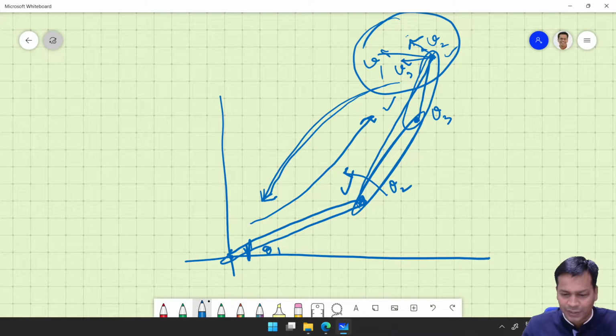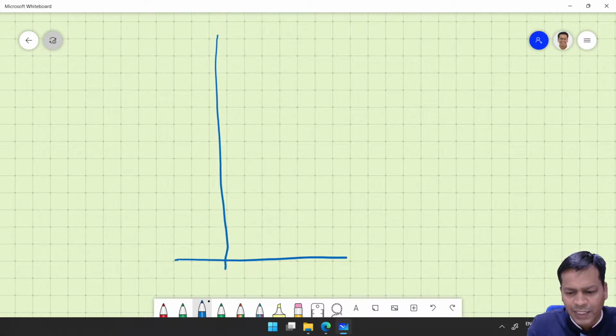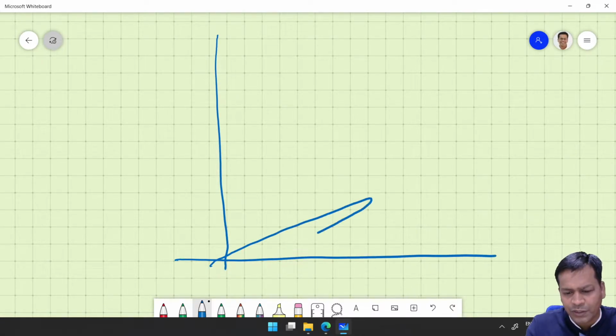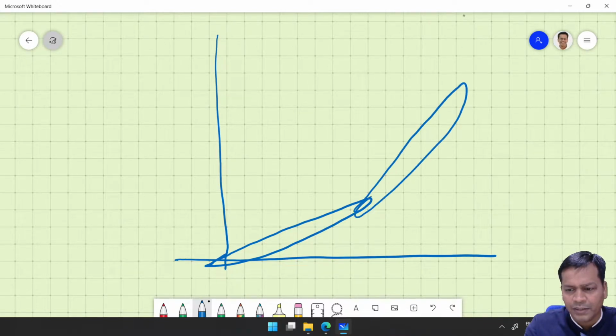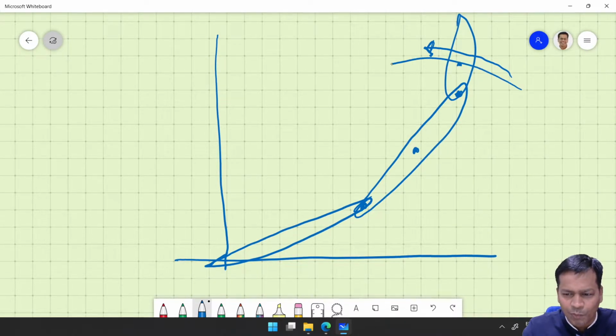Now what is backward recursion? Let me just go there. You have seen this earlier also when we were doing statics. So again let me draw the first link, second link, third link at least. The torque acting over here is because of the motion of this, is it not? Torque acting over here is because of the motion of this, so that is causing some torque. Again over here, it is because of the motion of this as well as this. So combined motions will create a torque which is here.